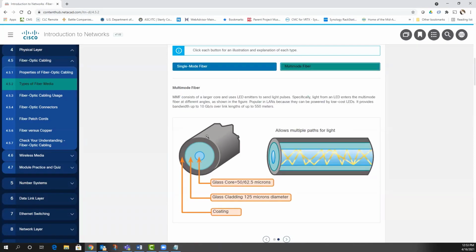Either way, never, ever, ever look into any type of fiber optic cable, even if someone on the other end has absolutely promised you it's not connected, because it can instantly destroy your retina. Do not. Only use testers when you're working with fiber optic cable. Don't even put it on your hand to try to see if the light will show in your hand, because technically it should not be able to burn you, but some of these lasers are very, very powerful.